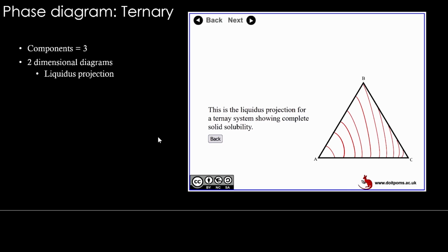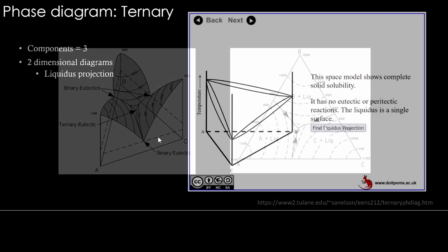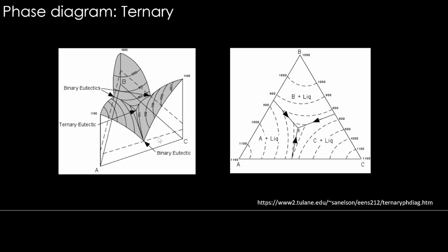What if on all the three sides we have eutectic diagrams like this? Okay, so all the three sides eutectic. There is no solubility for A in C or C in A. It's a system with almost no solubility in the solid state. Okay, so you can see at different temperatures how the contour lines look in the ternary prism, and there is a eutectic point here. It's going into the ternary regime like this, and there is a binary eutectic point. These are all binary eutectic points.